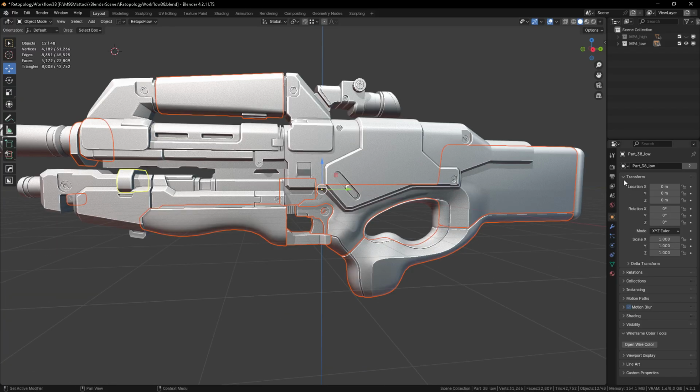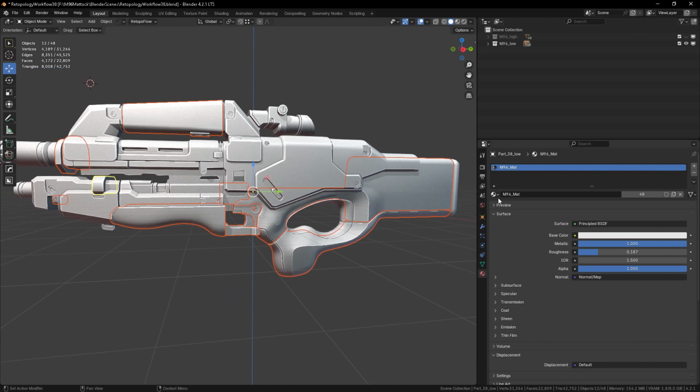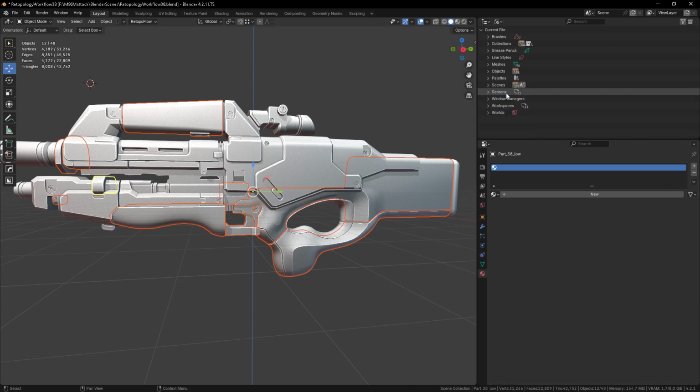Okay, let's switch to the material tab. And one thing you want to do is I'm gonna get rid of those materials. So to do that, let's click on this and click on Blender Files. So you'll see here Materials 2. Just click on this arrow, select these materials, right click, and delete them. So we have no material. Okay, and so let's create a new one,